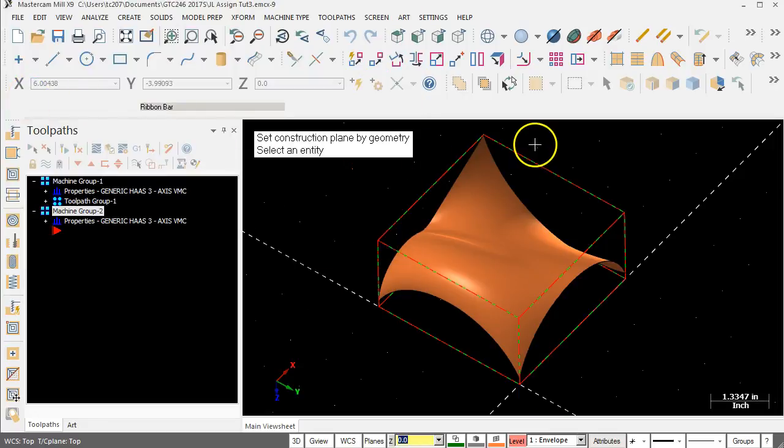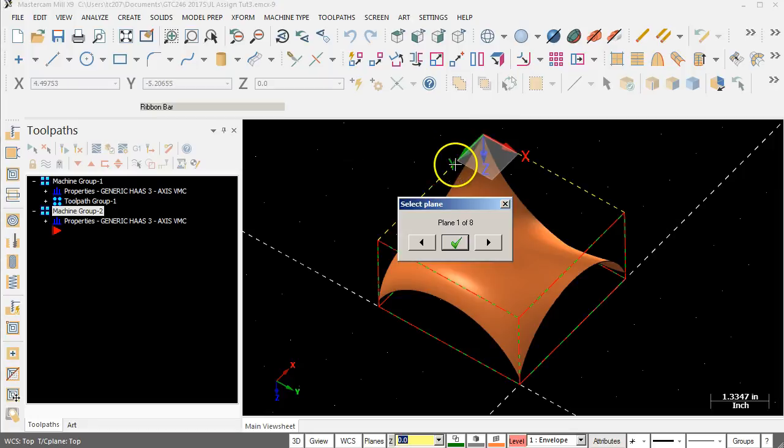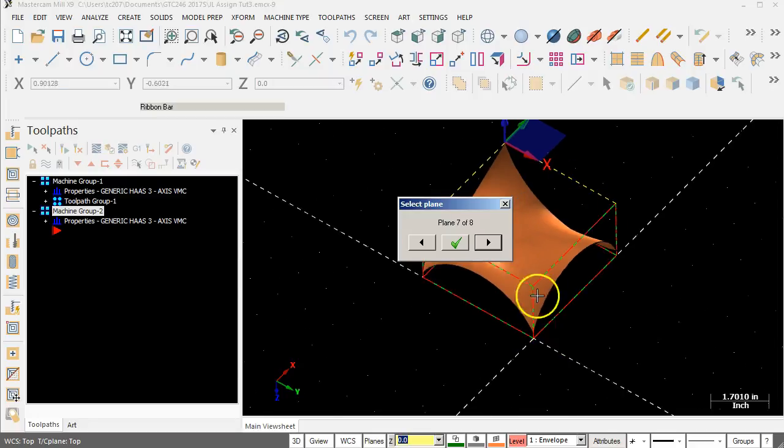My geometry then, did we pick, well, we picked up the other stock. So pick an entity, pick the second line. We're going to translate through until we find one that looks pretty good. All right, so based on my orientation, I'm picking up this origin and I'm placing it over on this corner.